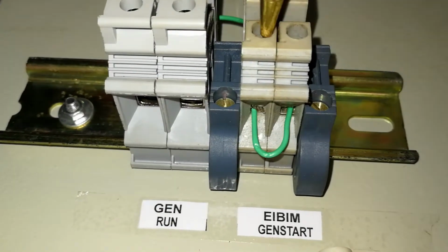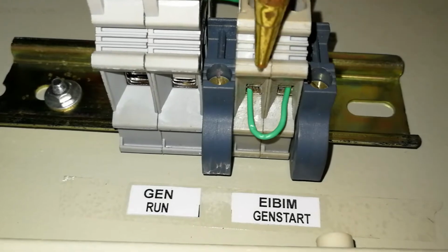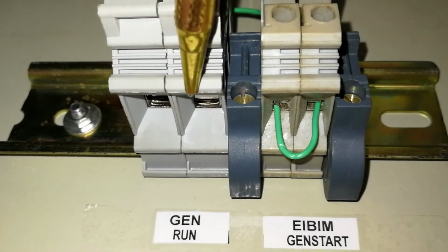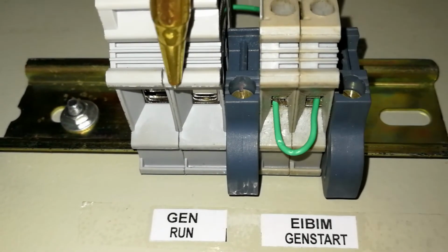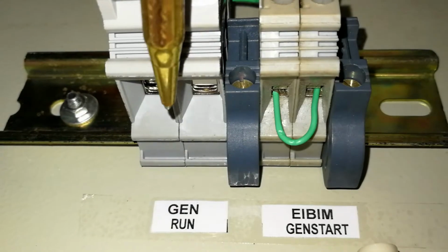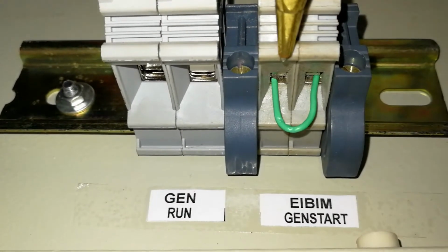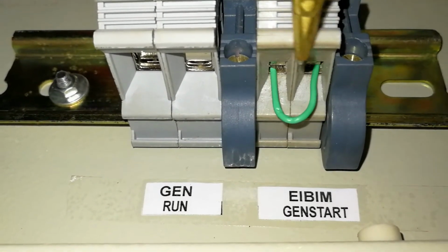On the other side, I have another set of terminals here, 2 of them that have been looped together. It's designed to communicate with the gen run or gen control terminal, such that when power fails, the ATS is not able to reach the generator in order to start the gen, unless a device that is attached here